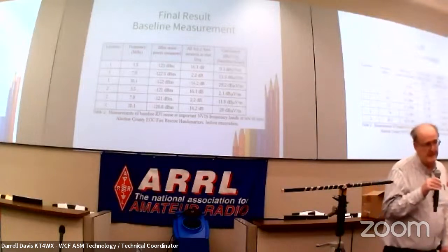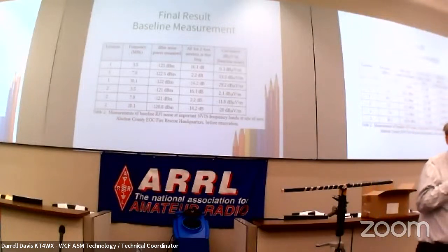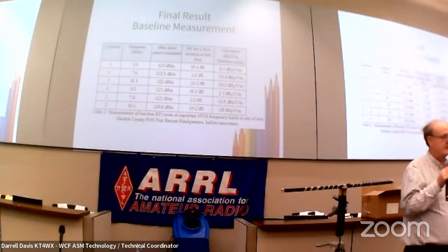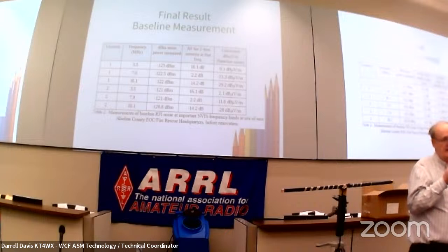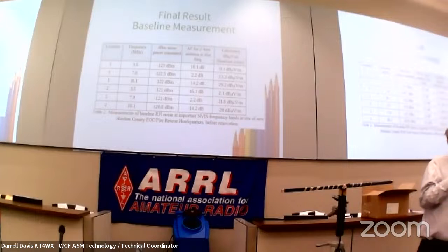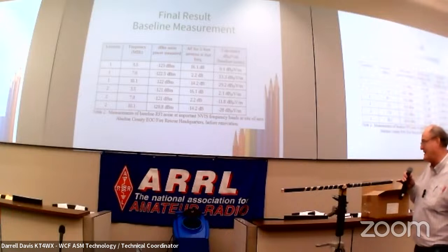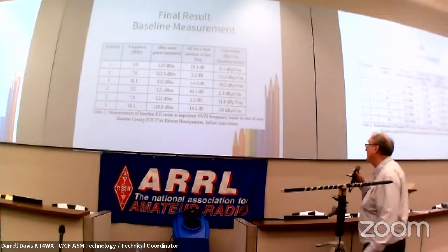You generally want to make these measurements at a 9 kilohertz bandwidth. Because remember, noise is white. The more bandwidth you use, the more power you'll pick up, right? So there's an agreed upon 9 kilohertz. The only problem is my cheap spectrum analyzer can't do 9. The closest it can do is 10. So there's a conversion you can use to fix that, but it's a very small fraction of a dB. It's not worth worrying about.